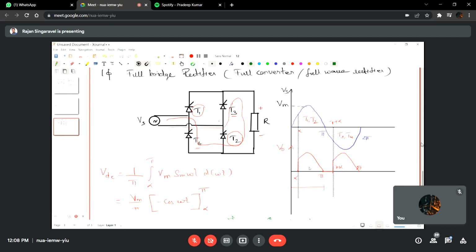So when you try to control, the output voltage will be reduced, not increased. Even though we call it a controlled rectifier, you can have control on only one side, right? The maximum output voltage will be obtained when alpha is equal to 0, which is almost equal to the working condition of a diode based full bridge rectifier without any SCR.